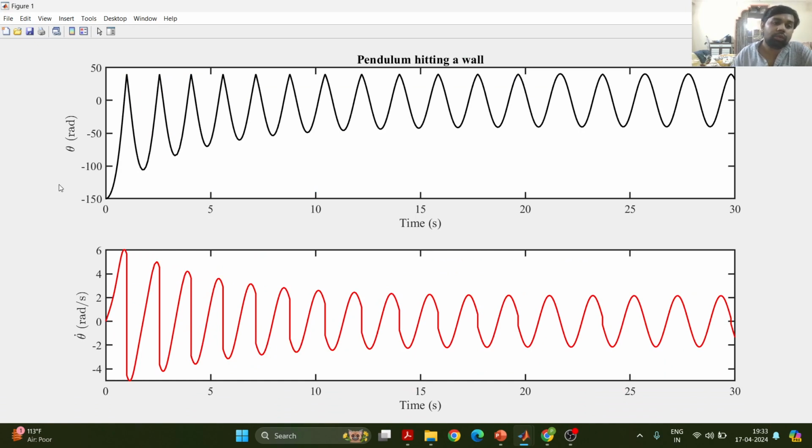For that, what we have to do is tell the solver that we have reached the wall, so now stop solving, and record the solution up to that time interval. Then the event of bouncing back, so we incorporate the coefficient of restitution, and then it's basically starting a new oscillation with a new set of initial conditions.